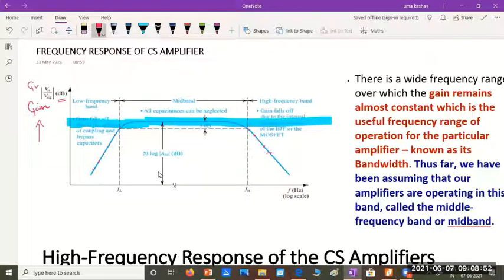So they came up with the idea of using a log scale for the frequency axis, where we get a complete picture in a smaller single graph sheet. So when I use the logarithm of the frequency values, we know log 10 is 1, log 100 is what? 2, right? 2. Accordingly, log 1000 is 3, and so on. So you would get the plot on a small scale and the complete variation can be captured effectively.